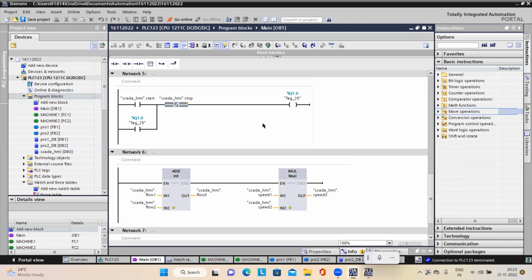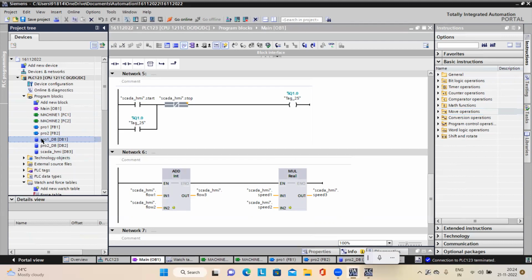Okay. So here this DB memory is used in terms of memory blocks. You can see the numbers here, DB1, DB2, right? Describing the DB number, DB3 like this. So in this block, this DB1 is assigned for FB1, right? In FB1, I have made a small logic. So how many addresses you are using, means parameters you are creating, and what is the type of parameter you are creating, like byte, word, or double word, it is taking that much of memory only.